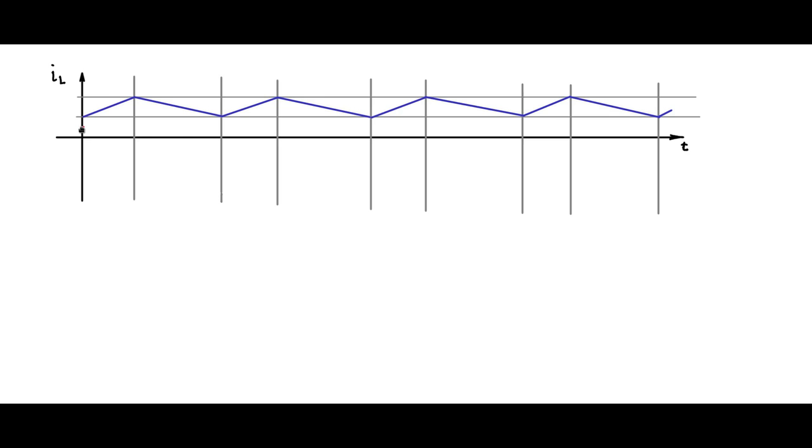And let's say if this disturbance occurs, the inductor current will start on from here. It's an integrator. It will start on from here with the same slope, Vin minus VB divided by L. So it will go parallel to this line. So let me draw it parallel to that line, and then after it hits this top limit, it will go parallel to the downslope of minus VB by L, then upslope, downslope, and so on.